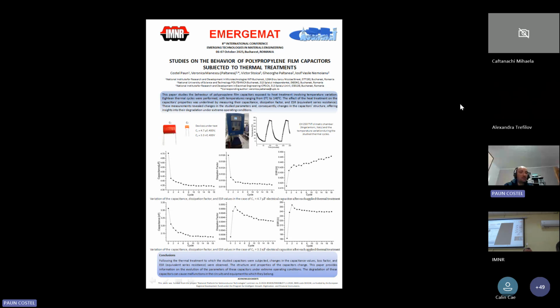18 thermal cycles were performed, as you can see in the first small graphic in the center upper part of the poster, with temperature ranging from 0 to 140 Celsius. The capacitor groups were subjected to accelerated thermal aging in a climatic chamber with a program for adjusting the temperature curve. The humidity was not controlled. The temperature in the device is measured with thermocouple sensors.